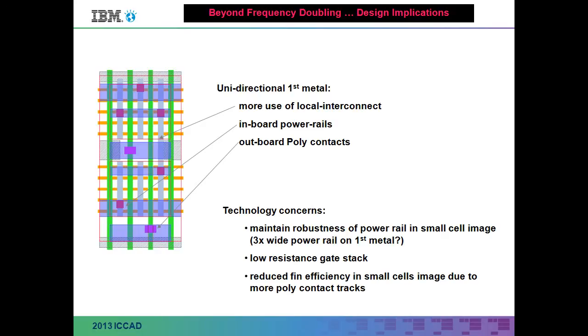But what this really means is, this can be done, but now it's no longer just design rule engineers and lithographers talking to each other. Now you have to worry about the gate stack, the device architecture, how you bring the power rails into your cells. Can a router deal with the fact that now your second level metal runs perpendicular to the cells, that the power gets dropped into the cells at sort of unpredictable pitches? So all of that requires some very fundamental optimization.